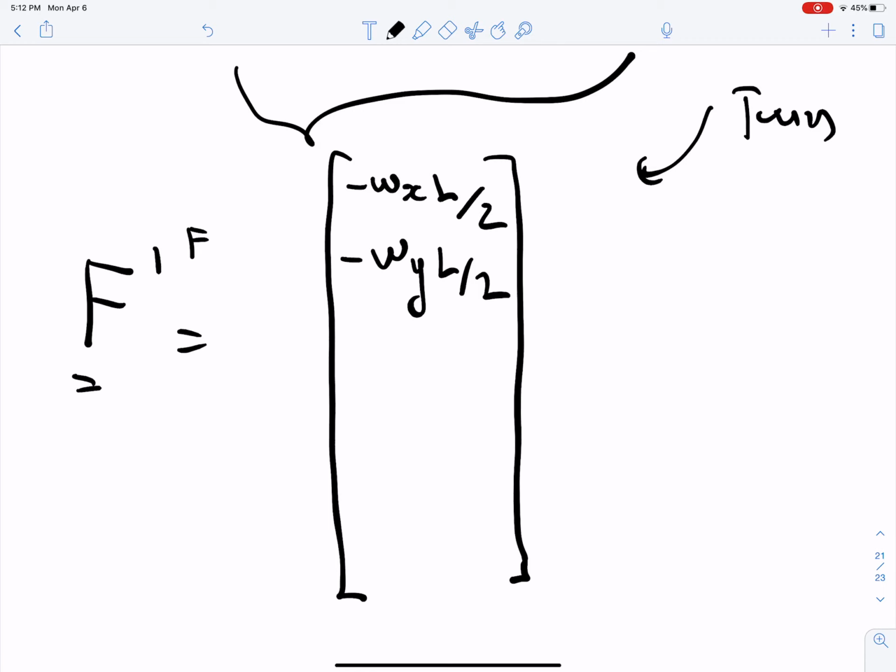And so the two are derived. It's interesting how the first one you derived for the truss, the second order differential equation, gave you that distribution of equivalent nodal loads. The second one, you derived from the beam differential equation, where you went through the moment and computed the forces by differentiating the moments.